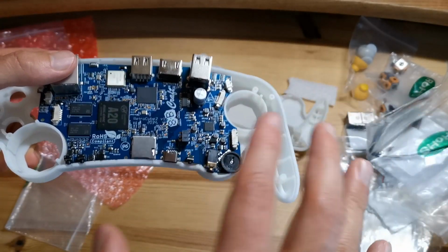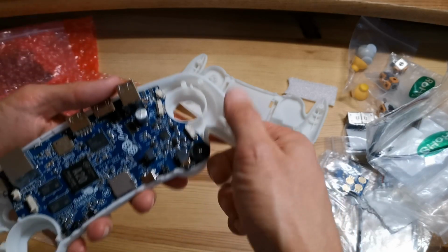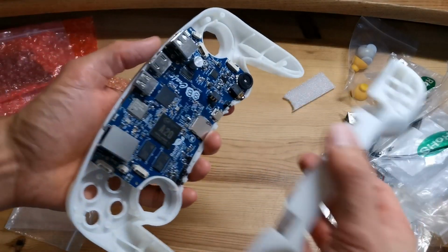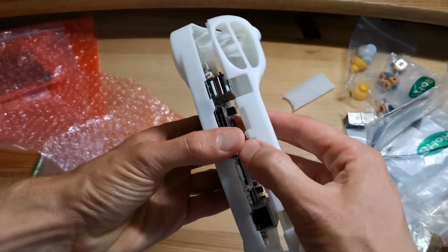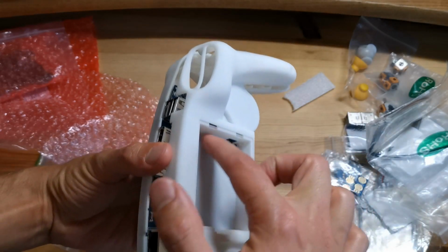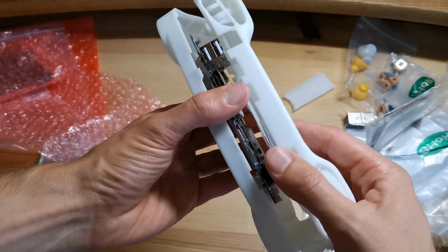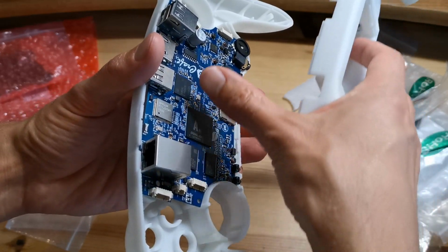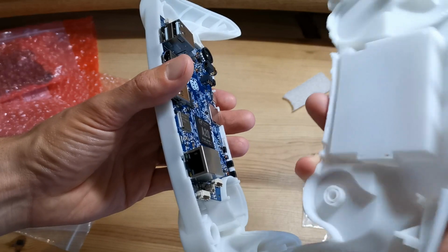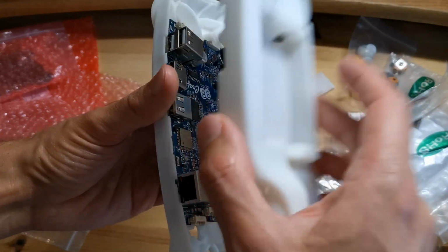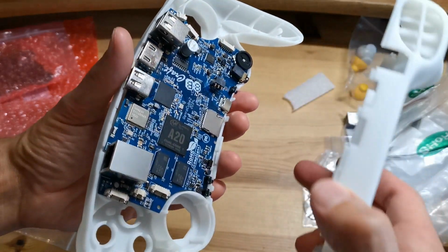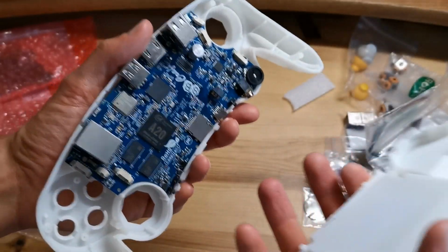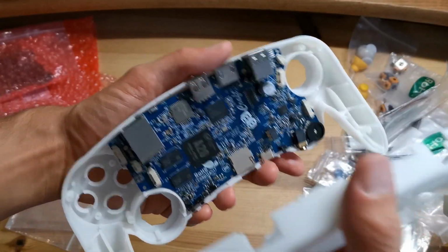And so the whole difficulty when you design such a project is that you have to position the connectors such that in the end you will be able to close the case. And as you can see here, we have a huge battery cavity, and the battery cavity comes very close to the inner components. It's maybe only 2 millimeters between the PCB and the battery components. So you have to be very precise in the positioning of the different connectors, and that's one of the most difficult parts, making sure that everything will fit perfectly.